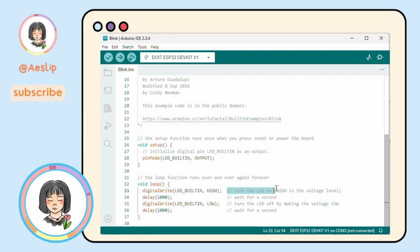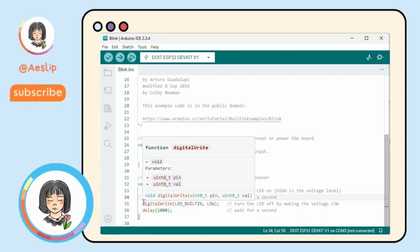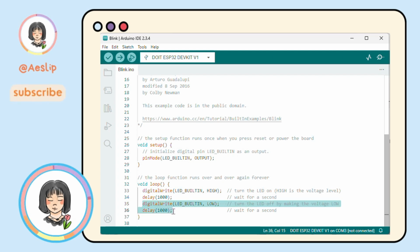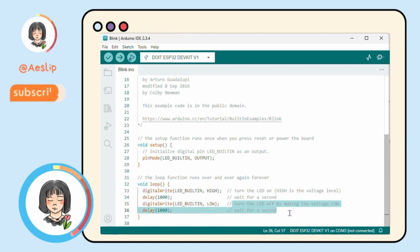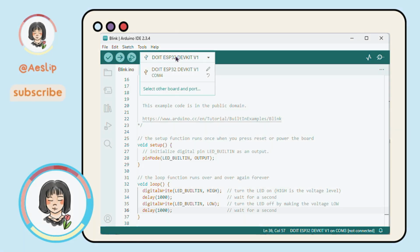This delay pauses the program for 1000 milliseconds, or 1 second. During this time, the LED will remain on. And here we turn the LED off by sending a low signal to the built-in LED pin. This again pauses the program for another 1 second while the LED is off.